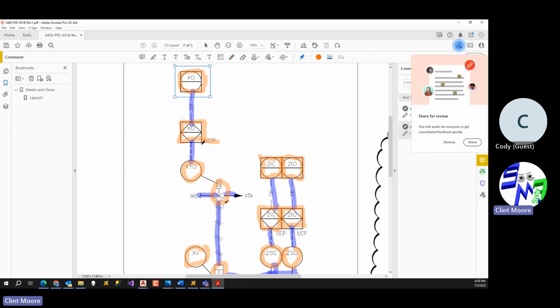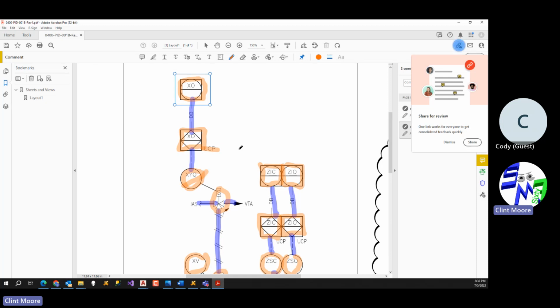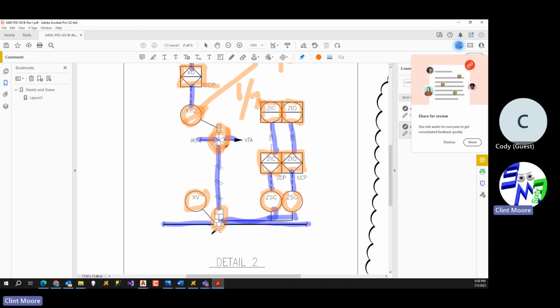This can be controlled by a layer. These are your blocks here, and you'd actually develop those blocks. Now we talked about this bubble being here would be a 1/2 inch bubble. This text inside would be 0.125, which is 1/8 inch text. And this here is a solenoid valve, or a valve. 9 times out of 10, you will have something like this, and this distance between here and here is typically a 1/4 inch. So let's draw that and see how that looks.